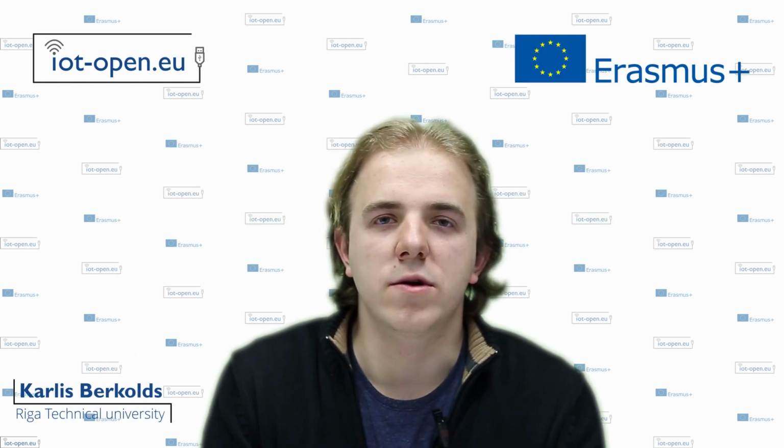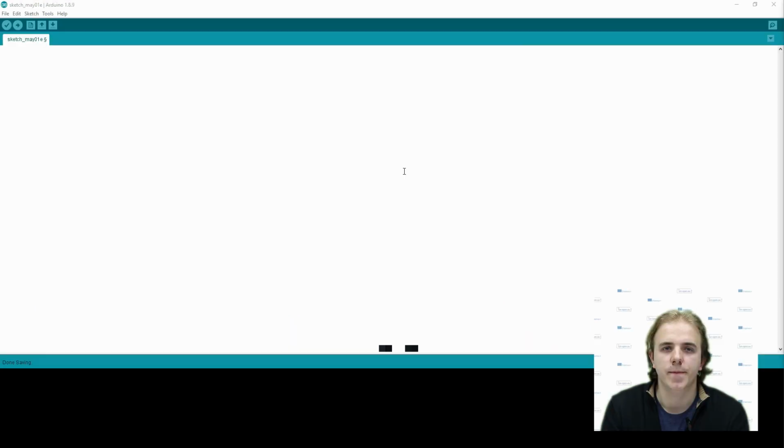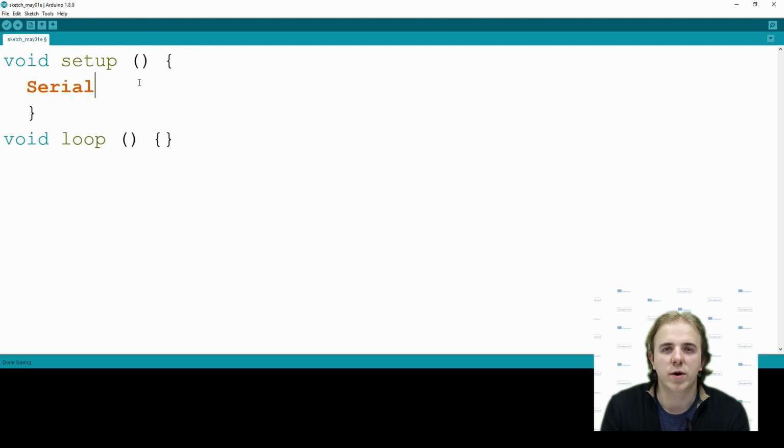In this video, we will talk about loop cycles that repeat parts of code continuously until the change of conditions. Each Arduino has the main loop function that repeats while Arduino is powered, allowing Arduino to respond to changes. While loop has a similar functionality as the main loop, and it can be used multiple times in the code. It works while the condition is true and exits the loop when it's false.